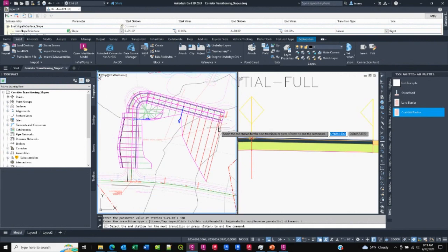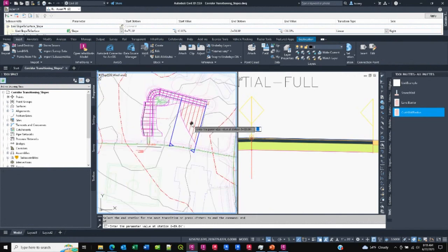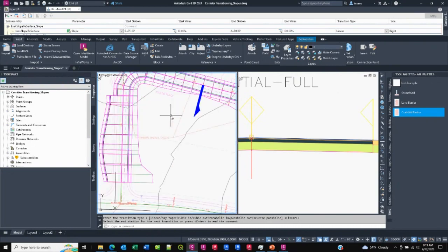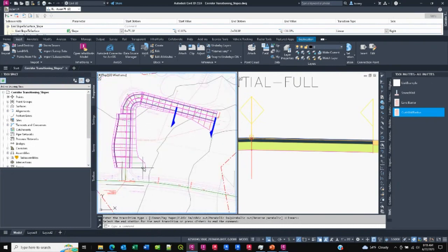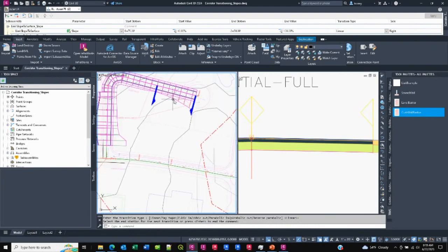Then I want to go out to the end here, and I'll just snap to this end point. By the time I get there, I want to be at 50%, so 2 to 1, and that's linear. Okay, I'm done setting those up. Now I can just say apply, and you can see how I've adjusted that slope so that I made it steeper, got around the inside of this curve here, came to the end here, and then changed back out to a gentler slope coming out this way.